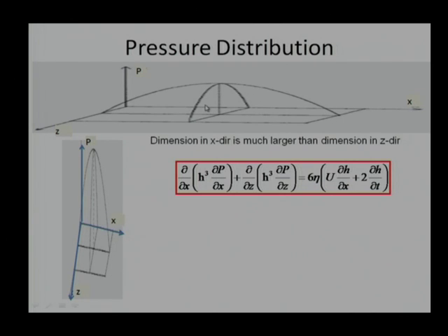So, the pressure distribution comes something like this. Now, what are we gaining from this? We are saying that the maximum pressure remains the same. As x value is more, dP/dx will be lesser. While in this case z is low, P remains the same, so dP/dz will be higher than dP/dx. That allows us to neglect one of these terms. If I say that the value of x is much larger, dP/dx will be smaller. In that case, this term can be neglected.